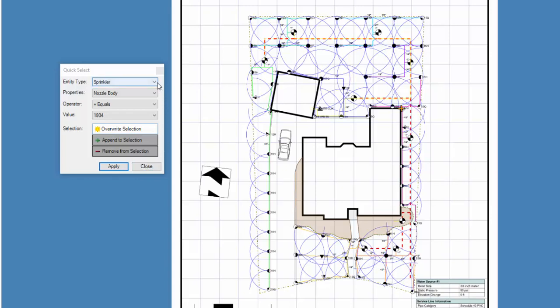We have symbol labels on this design. Suppose you want to move the labels to a different location in relationship to the equipment. You could delete the symbol labels layer in the Layer Manager and then replace all of the labels with the Auto Symbol Label command, or you can select the labels using the Quick Select command and then move them to a new location.